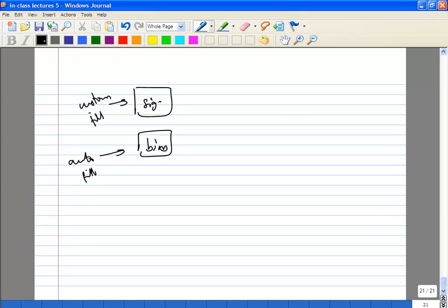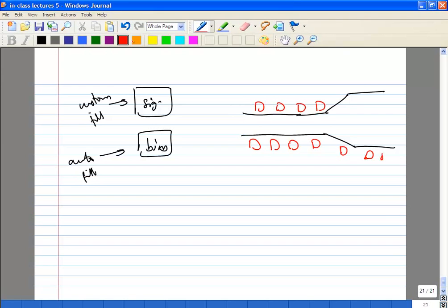And again, let's say you have differential lines. Again, you have to be very careful about the fill. Make sure your fill is symmetric. Something like this. Make sure it's symmetric. For example, don't fill on one side and not fill on the other side. Don't fill one side farther away than the other side. Those are all things you have to take care of.